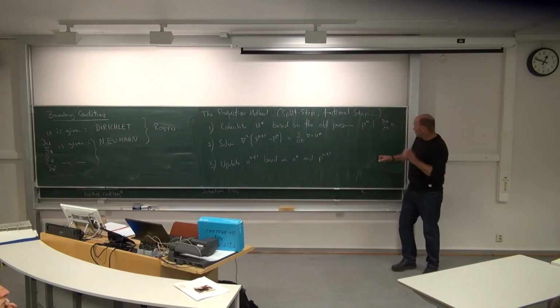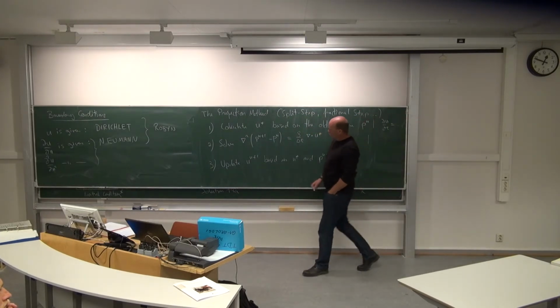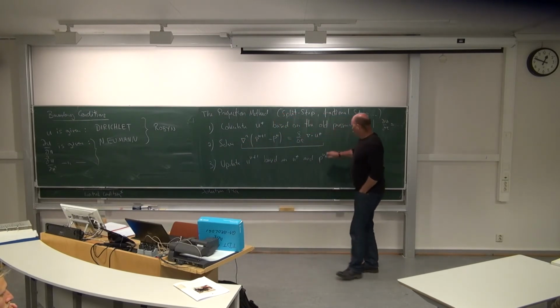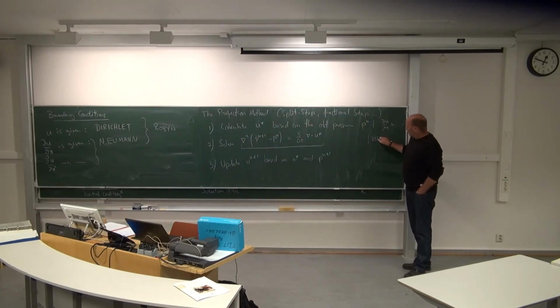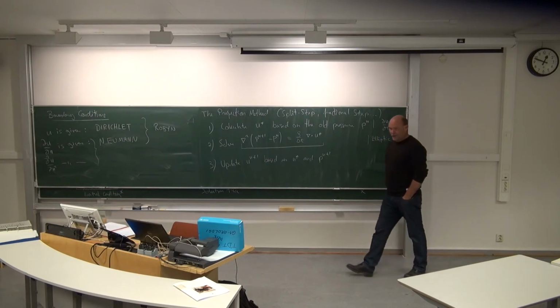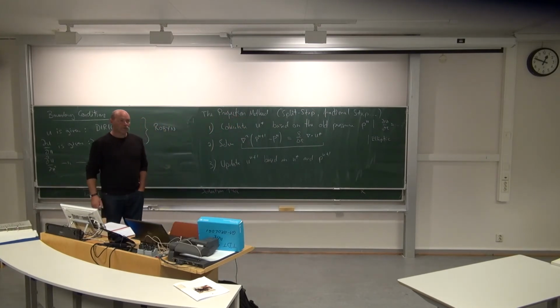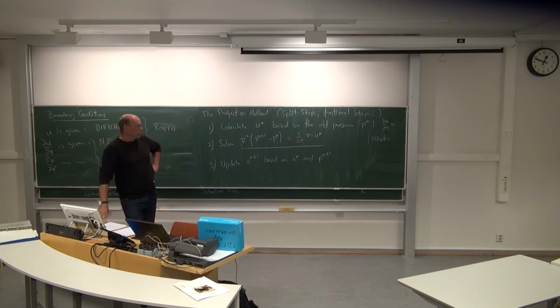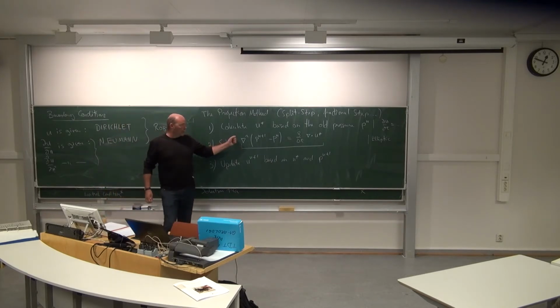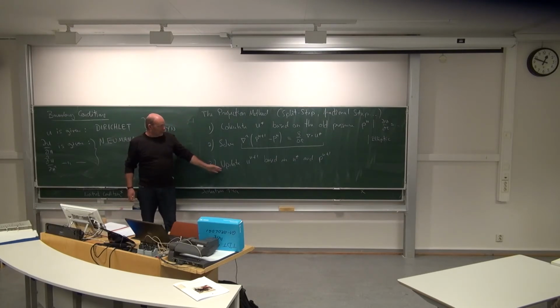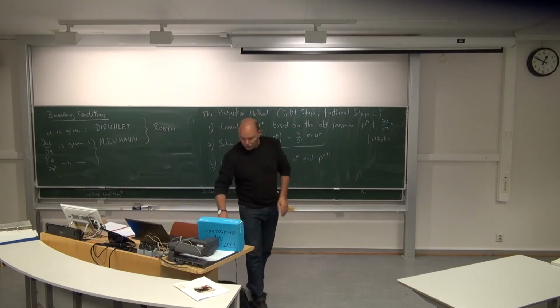The second equation, this one, this is the Poisson equation for the pressure. That one is elliptic. And that's the problem. Elliptic equations are expensive to solve. They are tricky. So here we are going to blow our CPU. Here we need to crunch some numbers. Finally, the last equation, that was also some variant of the Navier-Stokes. So also just one sweep for updating the unknown. So no problem there.